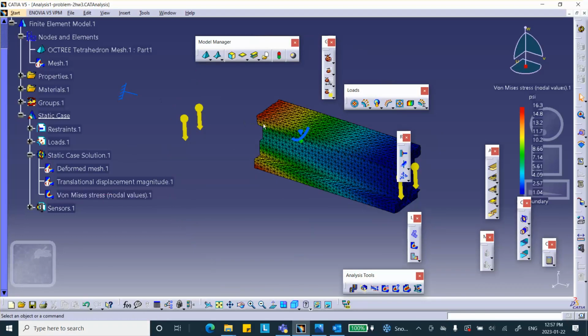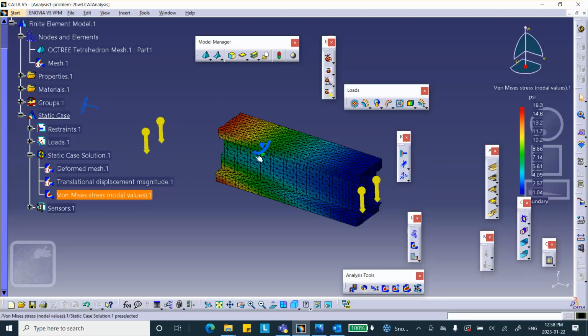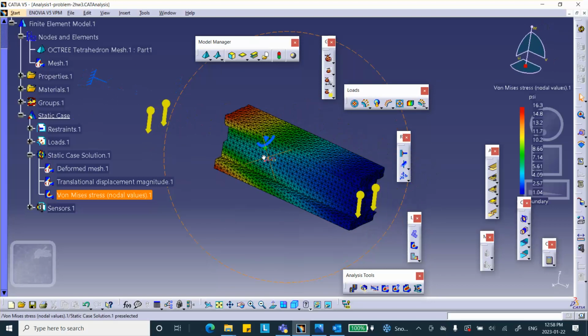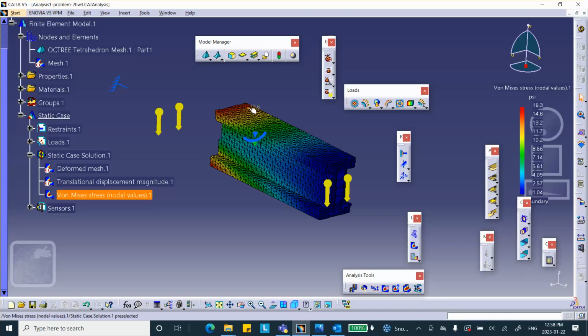you could not see these because you were too close to the end, and those big stresses at the wall would mask anything else. But anyway, that shows the stress distribution for the I-beam. It's not a secret that the top and the bottom bending stresses are maximum there. But of course, you have to be also careful about these edges where discontinuities may arise. Not quite discontinuity, it means rapid changes in stress concentrations, basically.